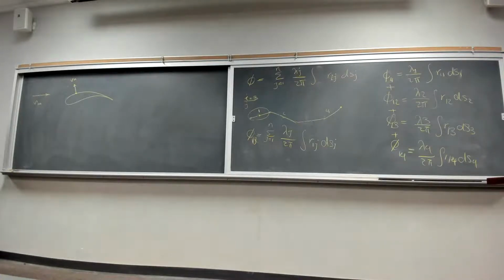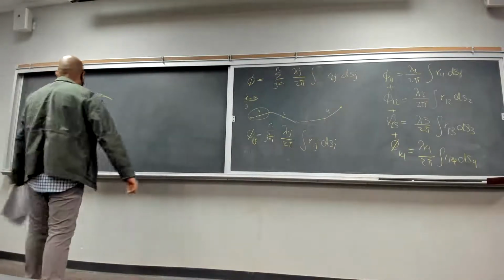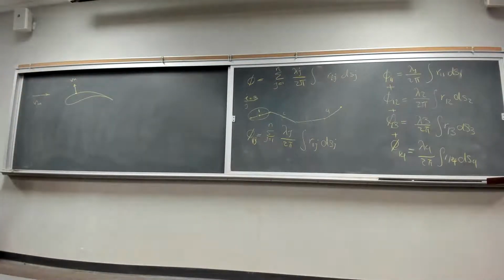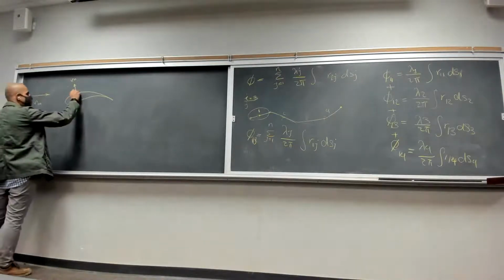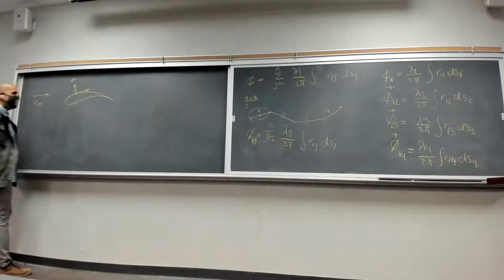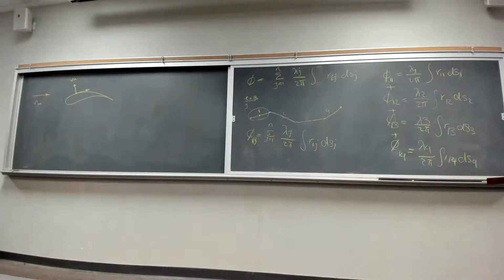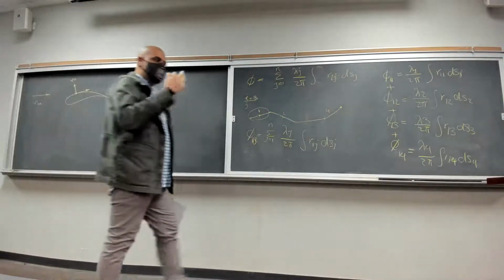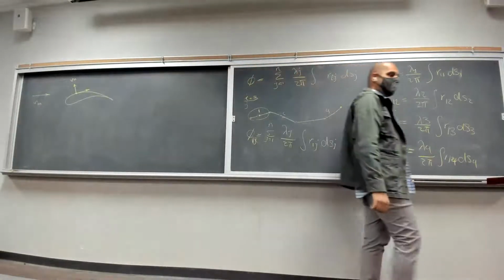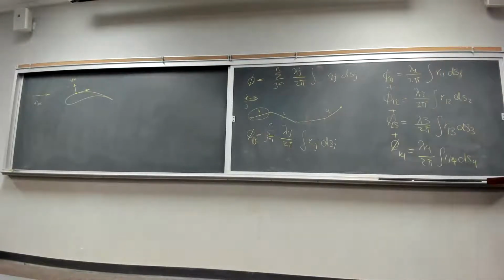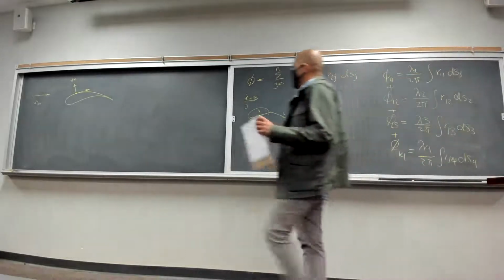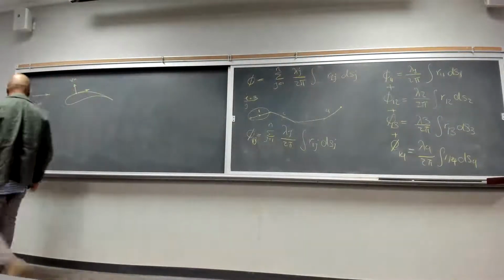Velocity normal to a wall is going to be 0. If you don't have any suction or blowing at the wall, velocity normal to a wall is going to be 0 at the wall itself. What about the velocity tangent to the wall? That one, in the inviscid incompressible flow, what did we say about the velocity of that one? We actually will get there. Let's just work with the velocity Vn.